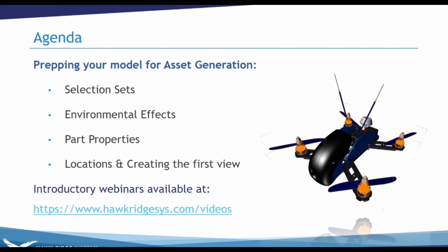we can take a screenshot, we can take a view of that. Any changes we make afterwards and want to update in that view, you can. And in that case, with all our properties that have changed, we're going to call that our default view, or also our baseline property view. So later on, if we make any edits or updates to our SOLIDWORKS model and push those through, we can then apply those properties back into our Composer file.